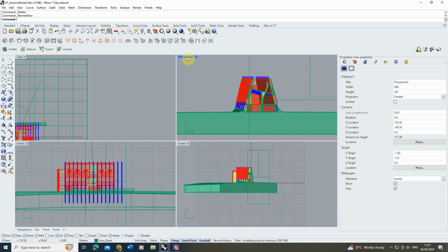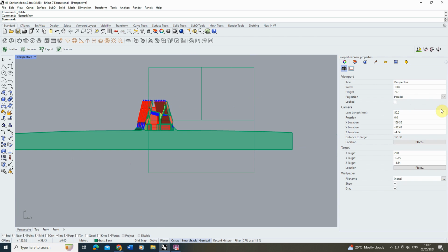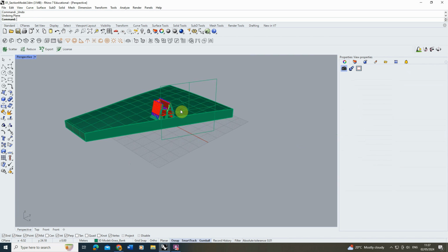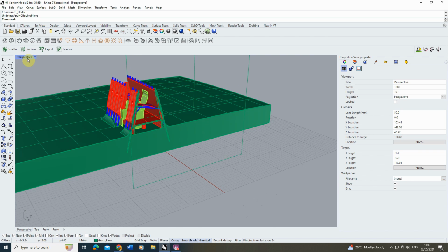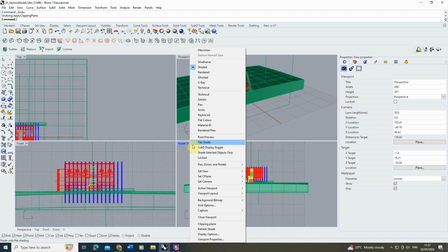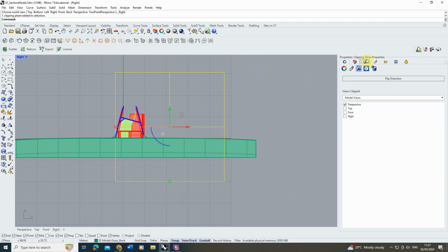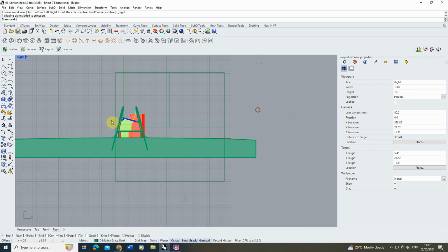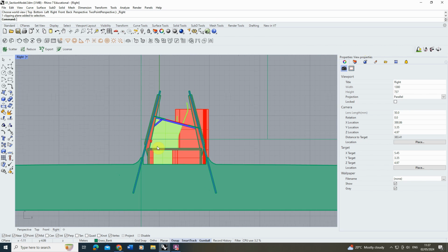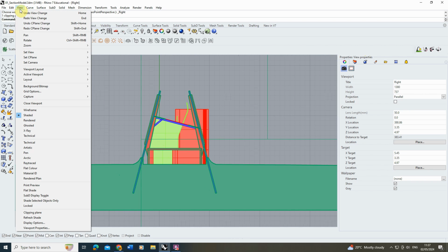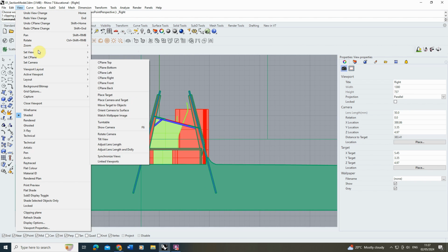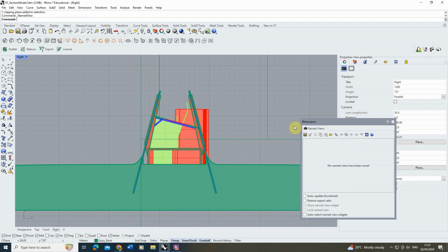Now for this particular example, we're going to go back with the standard projection we had originally. So we'll reverse it back around, and we're going to align it in that right hand view like we set here. Now once you've got your view aligned and you're happy with that cut line, as said before, we're going to save that as a named view, just so we don't lose it, and we're just going to call it section in this case.